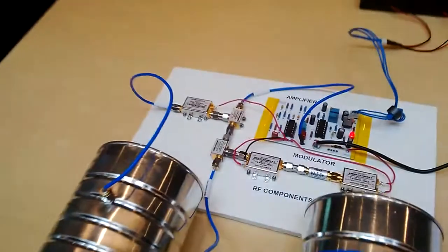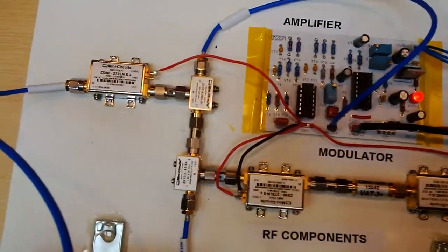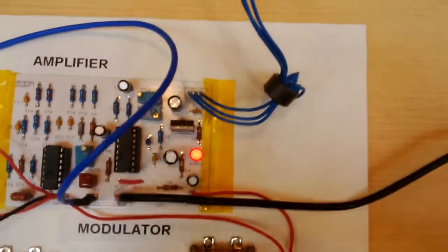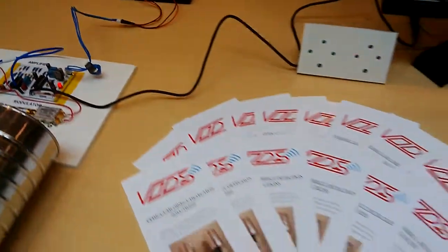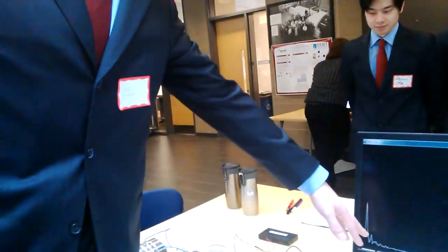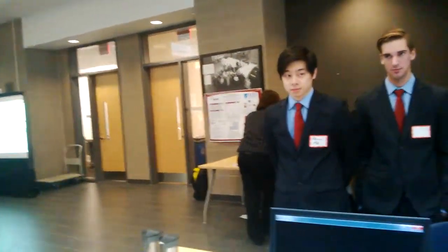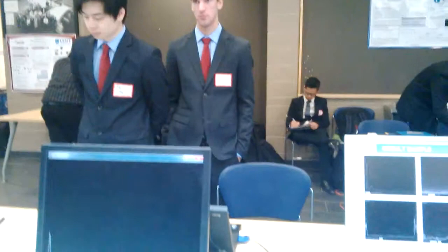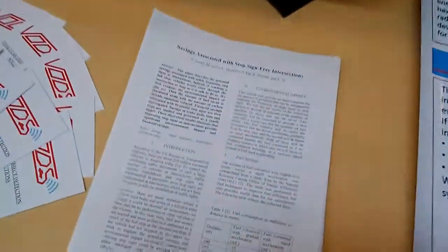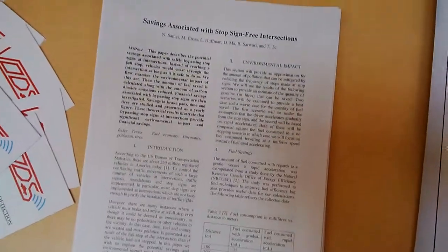So it sends a chirp signal which bounces off of the object in question. The chirp signal is received, and then we do a frequency analysis, which you can see on the monitor here. This is just the FFT. And we can actually track peaks in here. It's rather noisy right now as we've been having some performance issues, but we can track peaks which directly correspond to objects in the path. And from that, we can make a decision whether or not the user can pass through